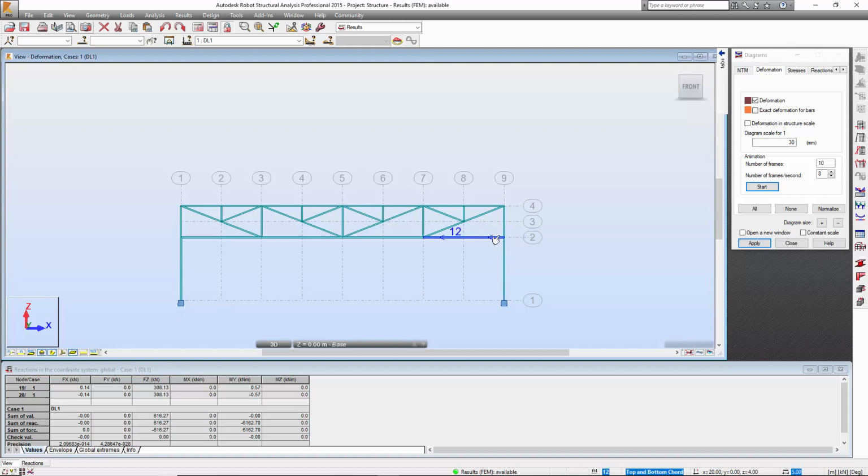What we're looking for later on, one thing that was very interesting that I'd like you to focus on, is the number 14. If you don't know which node we are looking at, you can also come to this point and click on the node number, so it brings back the node numbers for you. So this is node 14. We're interested to see the top of the column, and how much the deformation is going to be.